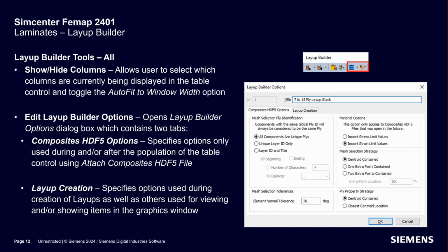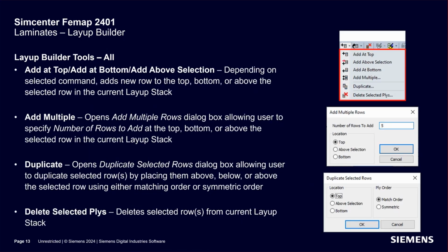And what you can actually do with these, a lot of times, if you just leave it as the defaults, you're going to get the most layups and properties automatically created as it can make. It's just going to have at it. It's going to take everything that you've defined and use all those values to the T and do that for you. So basically, what these options do is give you the ability to make fewer layups and properties automatically. But again, this is a totally different way to think about making layups in Femap.